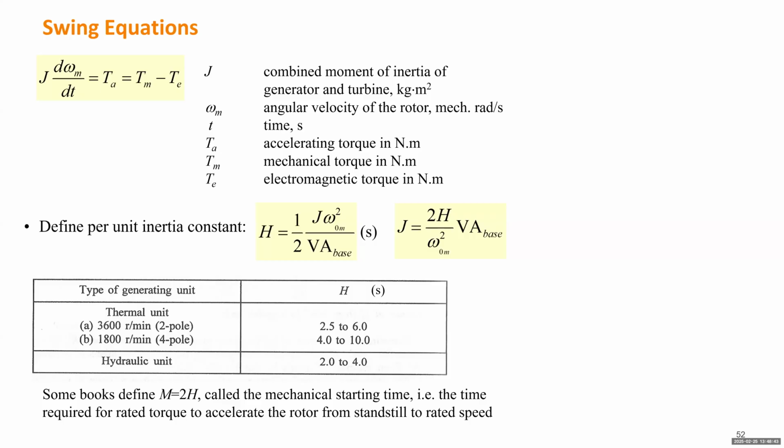Because speed does not suddenly appear when you turn on the unit. It will linearly increase from 0 to that value. So the time will be double. It's like you try to count the time by assuming the energy to be a rectangular area. Using the rectangular area for the energy divided by the power gives you the time. But actually, the speed increases linearly. It's a triangular area. So the triangle has to have double the length on one edge to give you the same area. So this time will be doubled.